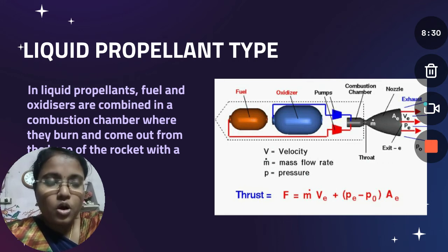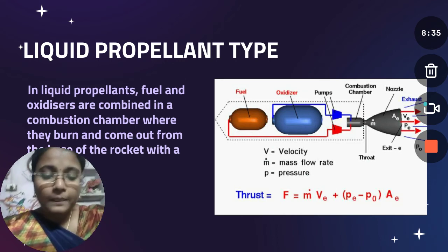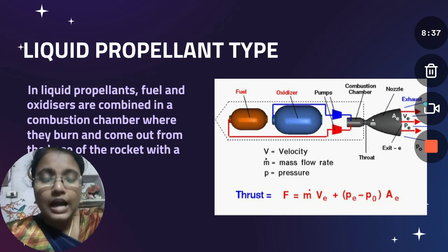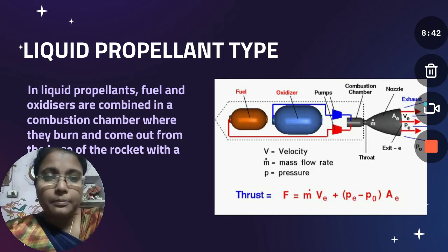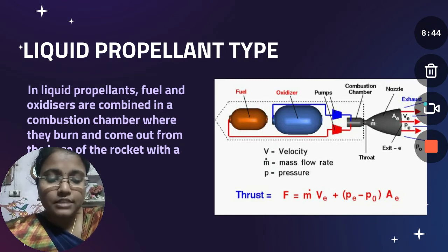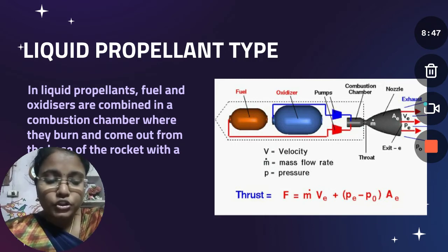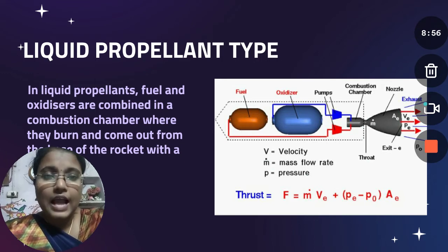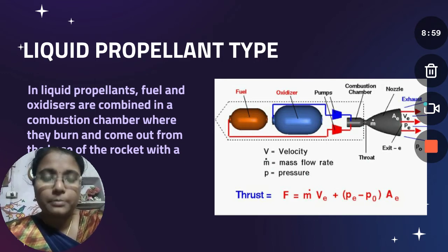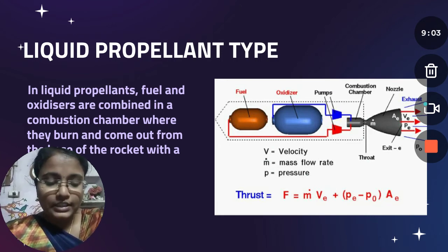Propellant flow rate must be extremely large for high thrust engines, often hundreds of gallons per second. A pumping feed system may require an engine delivering several thousand horsepower to drive the pumps. This power is usually developed by a hot gas turbine supplied from a gas generator, which is actually a small combustion chamber. The main rocket propellant can be used for the gas generator.